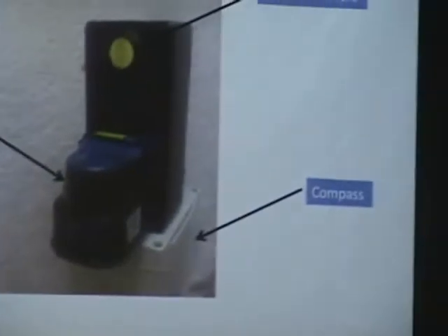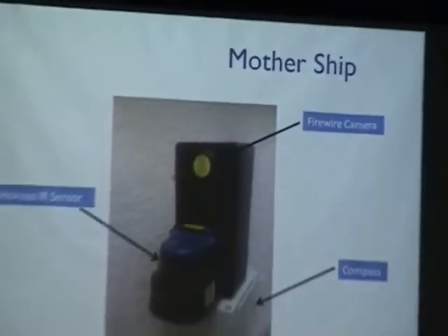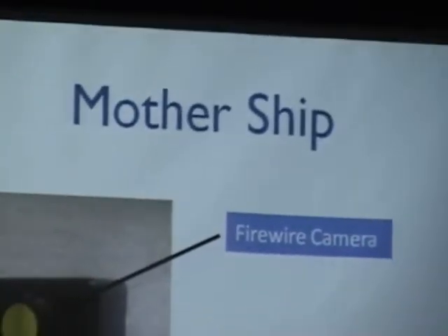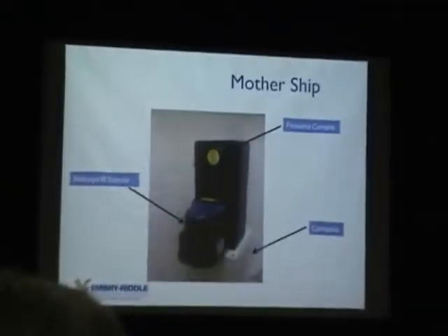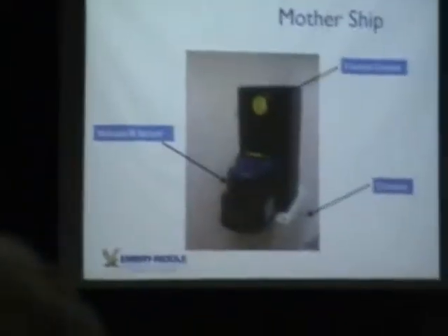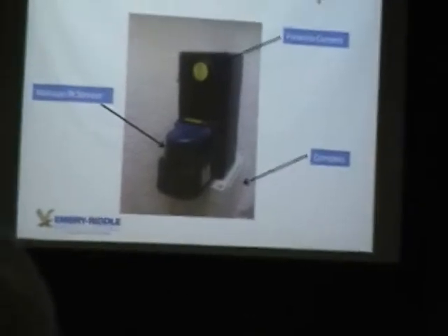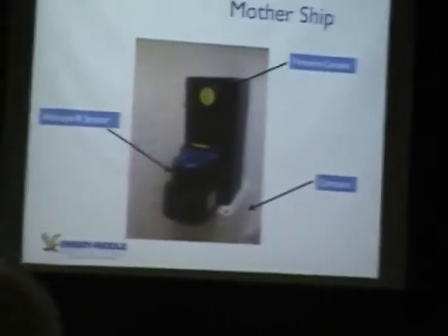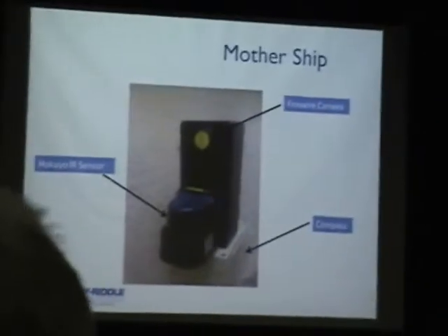For our initial ingress, we want a little higher resolution data. So what we do is we take advantage of the mothership being 3 meters away from the window, and we use a laser rangefinder to identify the bearing to the window, and then translate that to, again, a vehicle course in the time domain.